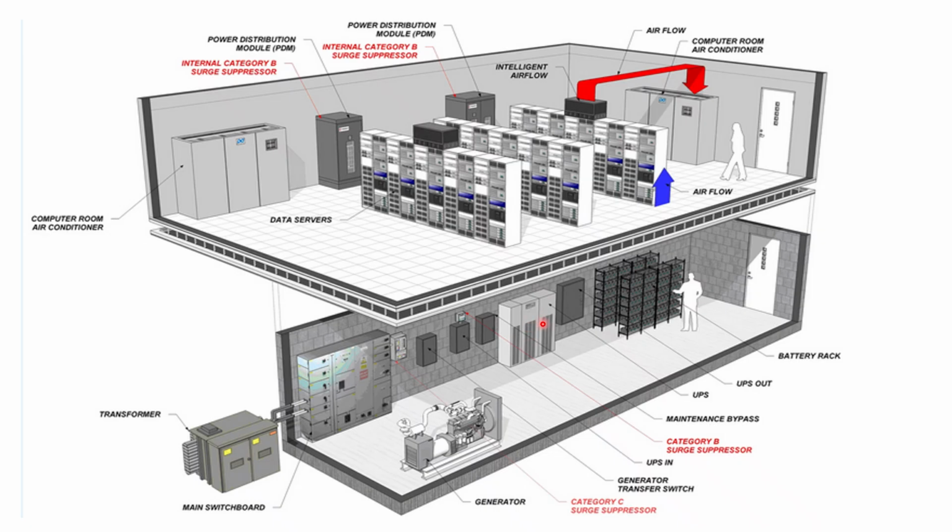When it is transferring its load to the generator, there are automatic transfer switches. They may go automatically, or you have to manually put them on. And this generator is normally supplied through a transformer. So the generator's half load may be the emergency load, and that is fed through the generator for hours together.